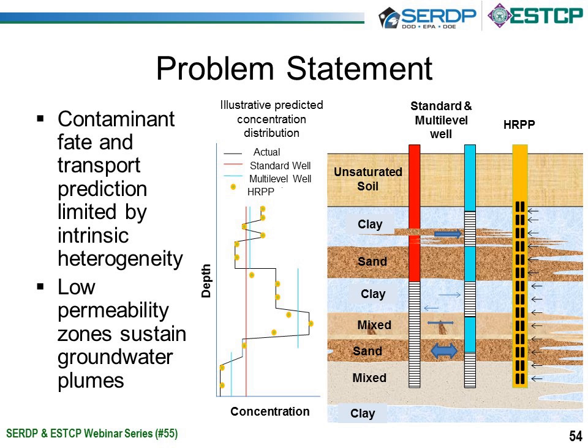So for instance, in the case where we have traditional large screened wells, this well screen is going to pull primarily from the most permeable regions, and so you're not going to get very good information about low permeability zones. Discrete wells do a better job because they can obviously be tailored to a more confined interval. But even then, as long as you cross two zones, you're still going to pull primarily from the more permeable zone. And in some formations, the zones are so impermeable that you can't produce water.